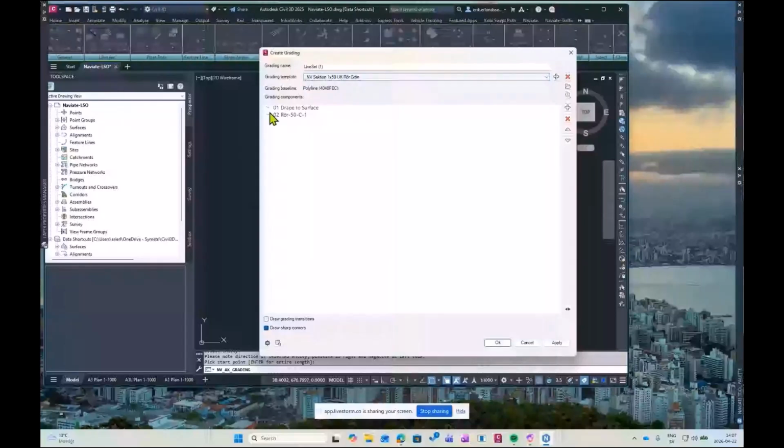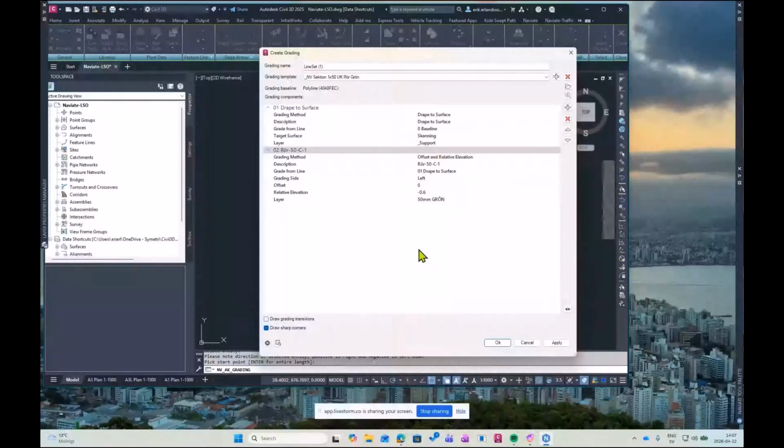For those of you that have used our line set, it's basically adding components, so it will do things in steps. So all of these templates I will go through, they will put the 2D line as a draped line on the surface, and then it will create a line from the draped line as the line where we will create our solids from and put them at the relative elevation. So with the coverage we want. So let's go ahead and press OK.